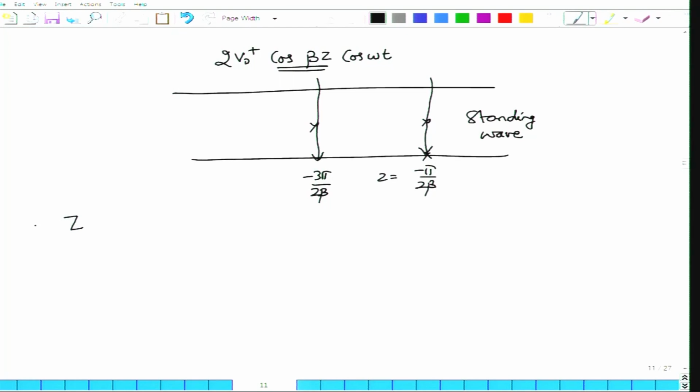Alright, let us consider the second case. I consider ZL is equal to 0, which happens to be the short circuit condition. In the short circuit case, I know that the voltage would actually drop down to 0 and the current would actually be maximum there. But what would be my load reflection coefficient here? Gamma L will be equal to minus 1.